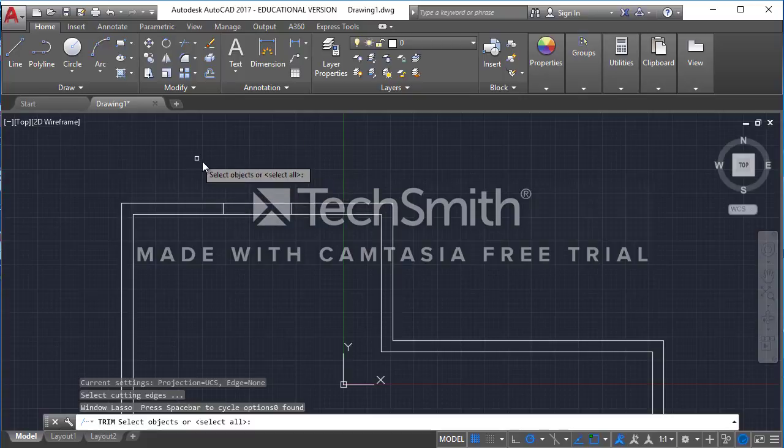Okay, so notice that right now after I typed in TR for trim, it's telling you to select the objects. It says select objects that you want to trim. Okay, so what I'm going to do is I'm going to click one time and I'm going to select the region that I want to trim.